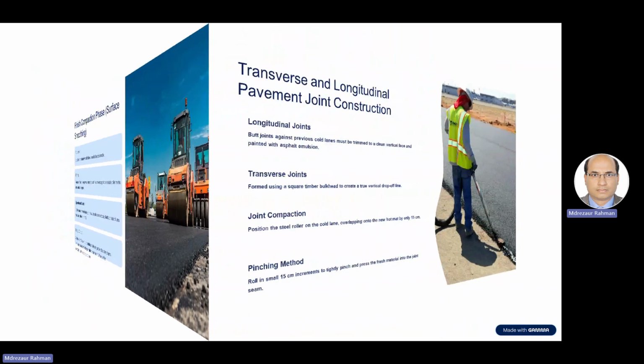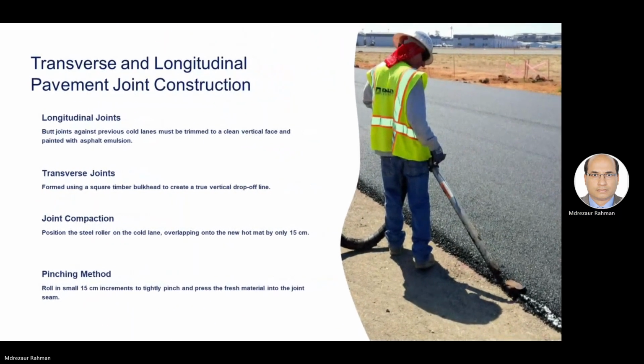Okay, next one, for the joint. But one thing, for compaction, one thing we're not mentioning: how many passes, 30 to 40 passes? It is not mentioned, it depends on satisfaction. 3 to 5 hours of rolling, continue rolling. It's not mentioned in the specs, but it will be done based on the trial and experience before, and that will be decided for the permanent work.